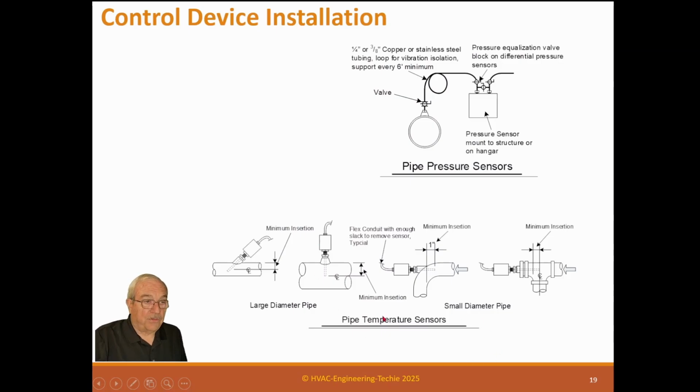Now these are thermal wells or temperature sensors. And I would get control contractors who would tell me why there's not enough room to put the sensor well in the pipe. So I had to build a deal. So what they'll do is they'll come over here and if this is the pipe running here, they'll build a bunch of reducing couplings and have this well sitting way over here where the well doesn't even go into the pipe.